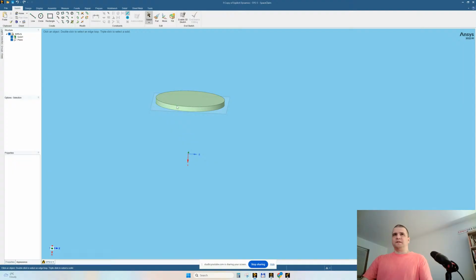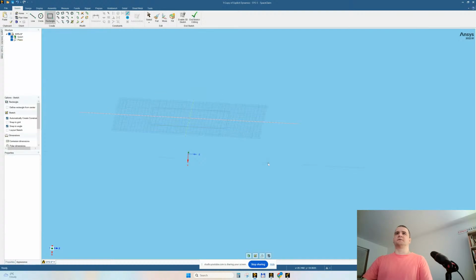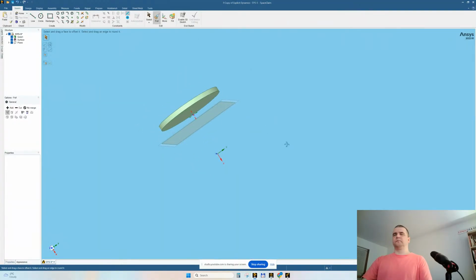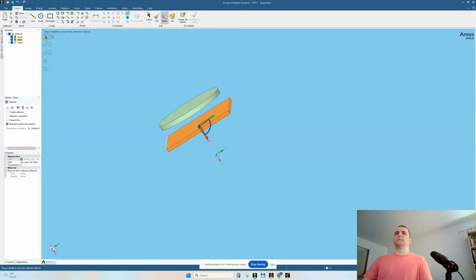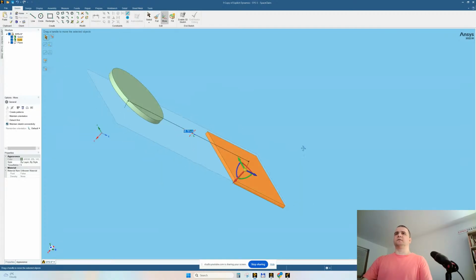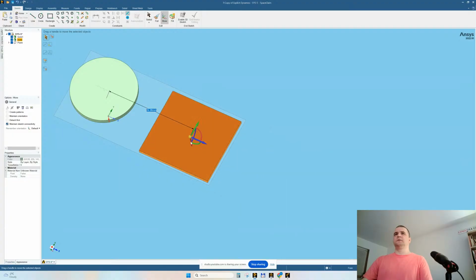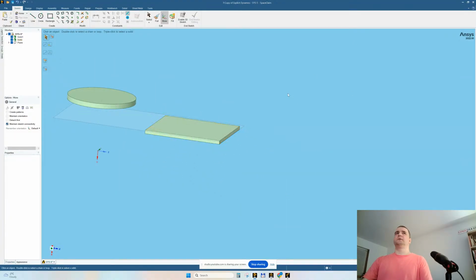Small secret: we do Cartesian mesh when we cannot achieve hex mesh. This is a small secret, yes? It's like a small, desperate measure. I'm not saying that our colleague used it out of desperation, but it can be used out of desperation. No problem.